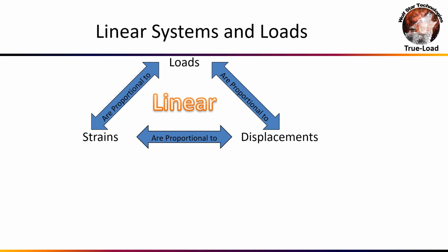The loading can be as nonlinear as anything. It can be sinusoidal, ramp loading, impact loading, that's okay. We just need the strain response to remain proportional and linear to the loading.